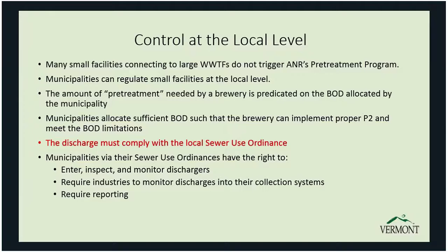Now, you may not need a pretreatment permit, and many small facilities connecting to large treatment plants do not trigger our pretreatment program. Municipalities can regulate small facilities at the local level, and the amount of pretreatment needed may be predicated on the BOD allocated by the municipality. As long as municipalities allocate sufficient BOD such that the brewery or facility can implement proper pollution prevention and meet the BOD limitations. Of course, the discharge must comply with the local sewer ordinance,